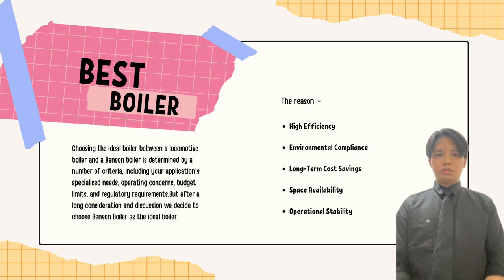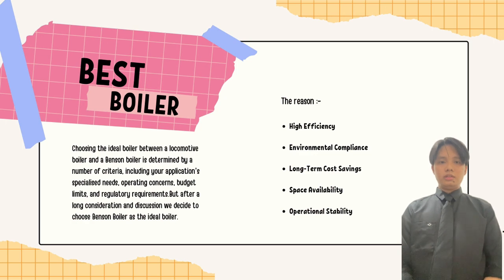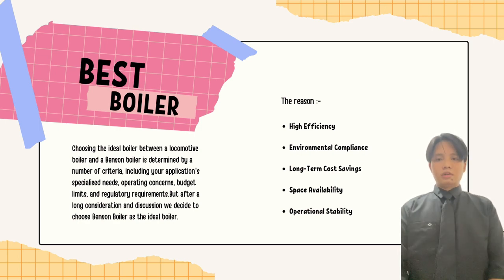Benson boiler operate at supercritical pressure and temperature, providing higher thermal efficiency than locomotive boiler. The second one is environmental compliance. Benson boiler can be outfitted with innovative emission control technology to reduce environmental effect. If regulatory compliance with emission requirement is an important consideration, a Benson boiler may be a better fit for your needs.